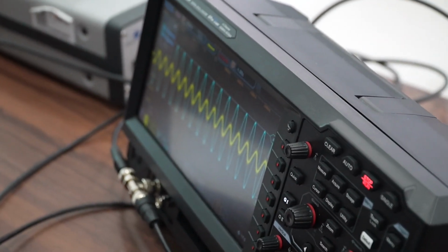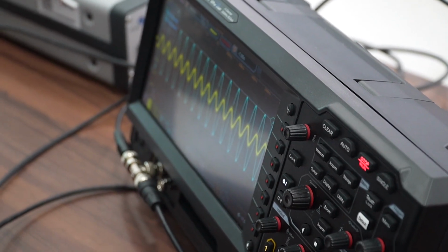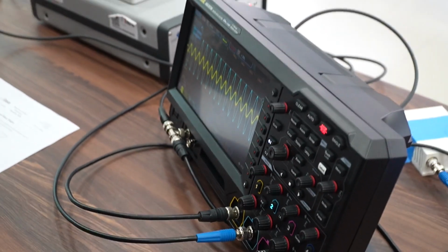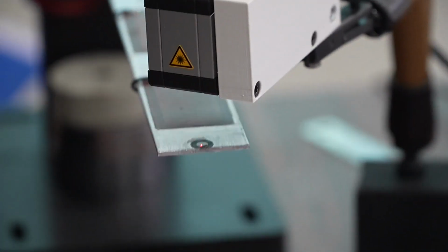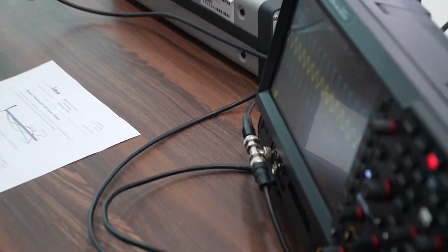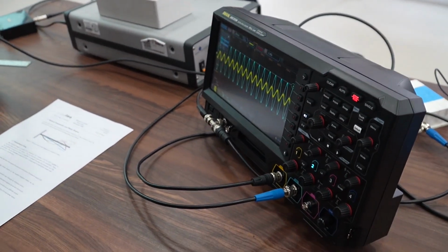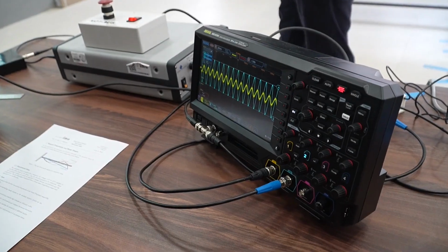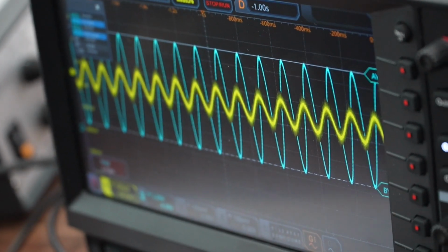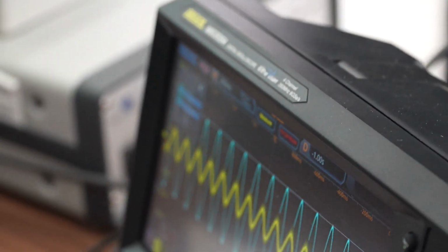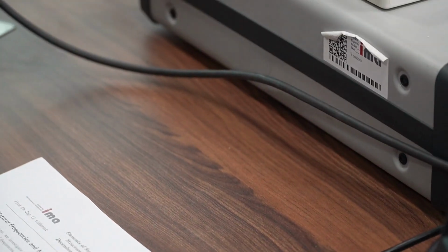And now you see, anyway, you see that static state 0, first eigenmode tip deflection 4.25, second mode tip deflection only 0.12 millimeter. So the higher the frequency goes, the smaller the deflections will probably be. Okay? Now what you could do is, now you do the same thing here, here, here, and here.